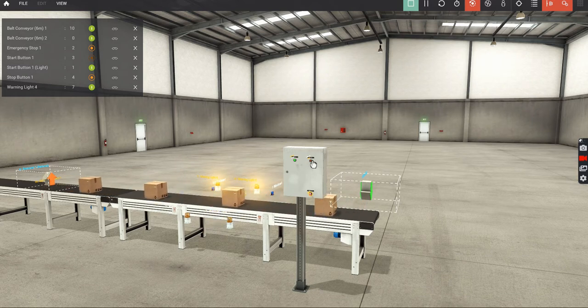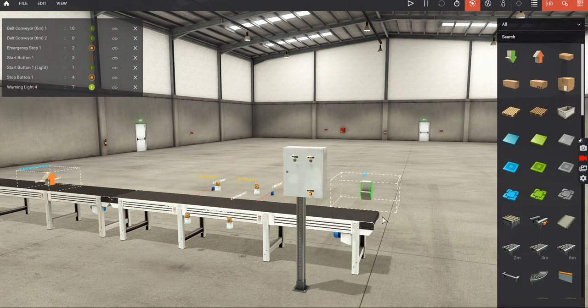And if I press the stop button, it's gonna stop. If I start again, it's gonna start from where I stopped it. And the emergency button is gonna stop everything, including the arm and the pneumatic cylinder, and they're represented by the lights in here. So the lights are off, and I have to release the emergency button before starting the program again. So that's for Factory I/O. And now I'm gonna stop that.